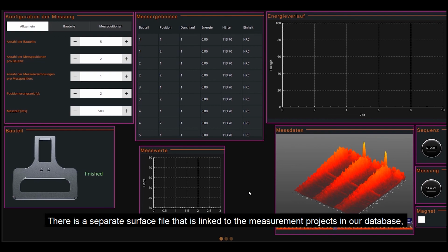This enables us to use the complex evaluation algorithms such as spectral analysis, air gap measurements, pattern recognition in the non-contact evaluation of component hardness and stress states, which we use for hardness measurement in a simple user interface.